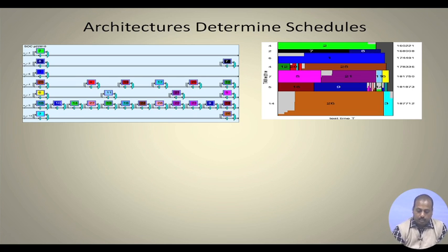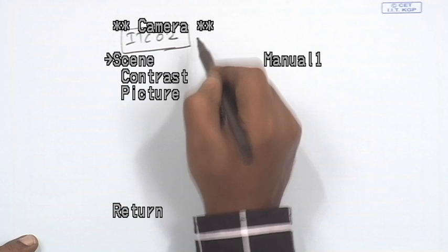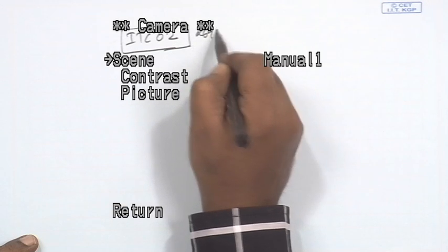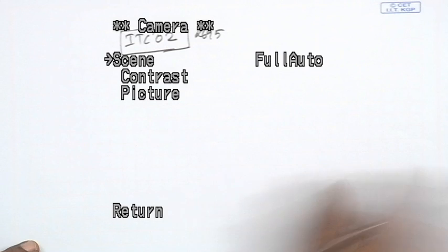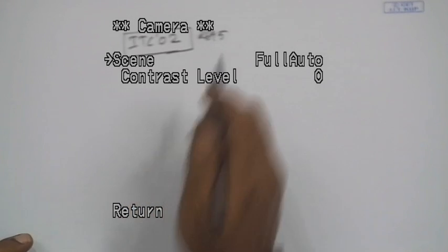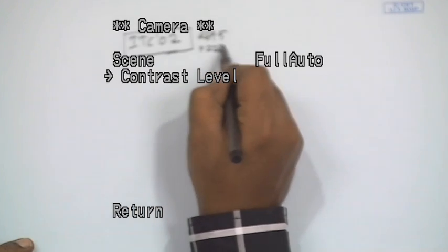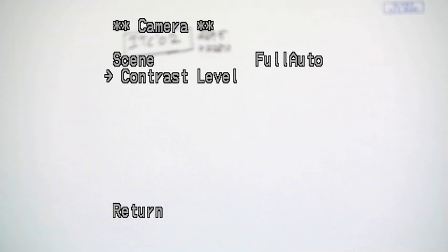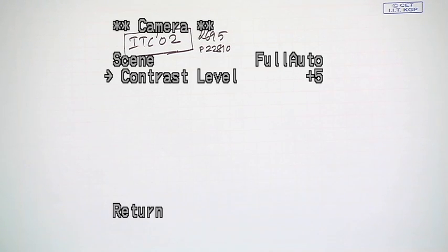They are called ITC 02 benchmarks. This ITC 02 benchmark has a number of SOCs in it. They are the SOC benchmarks, and there are many such benchmarks in it, like it starts with D695, then this P22810. So, this is another benchmark. These benchmarks are often used for testing the different test algorithms for this purpose.